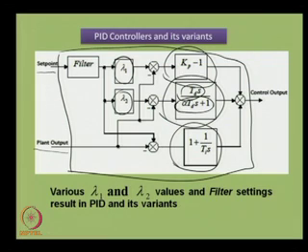Similarly, the integral controller has been put in such a way that, if you look at this, you can make out that basically the integral controller is available in the inner feedback path of the system, avoiding integral wind up action. So, to initiate anti-integral wind up actions, one has to have different types of controller configurations. All these things we shall study in lecture 3.